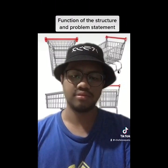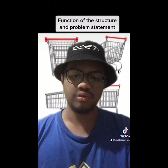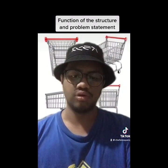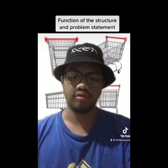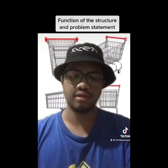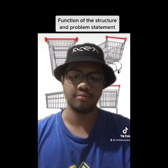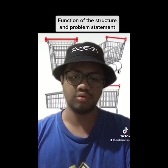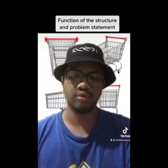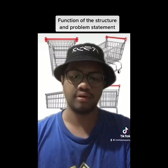Then it becomes a truss or frame-like problem. The two wheels will act like two rollers providing support traction. Apart from that, there are two steel rods slightly inclined just below the portion where all the objects will be kept. The rods act as supports to the lower portion of the base where all the items will be kept.